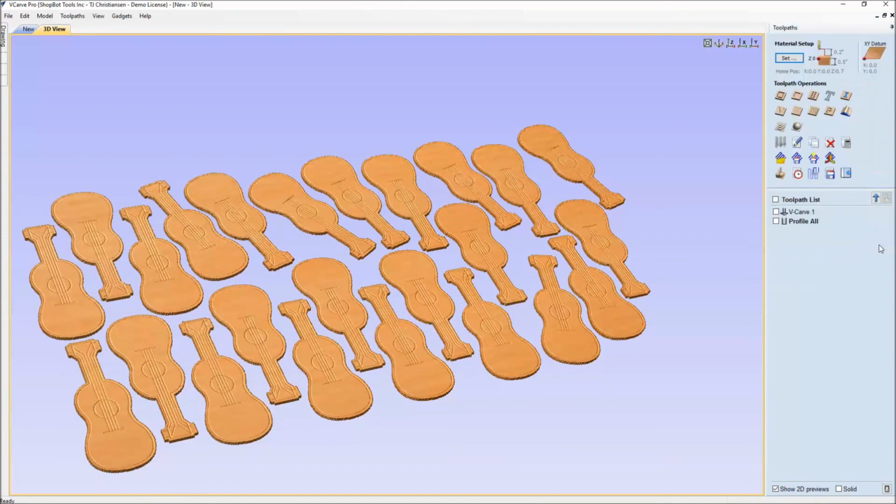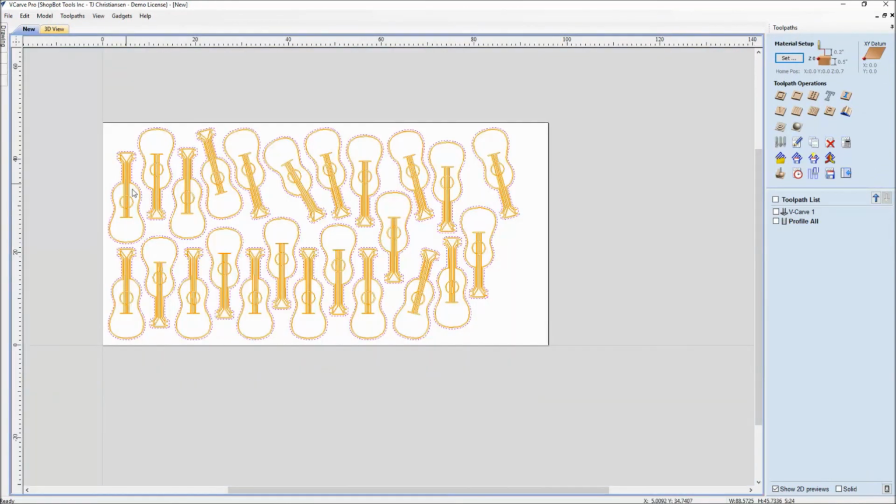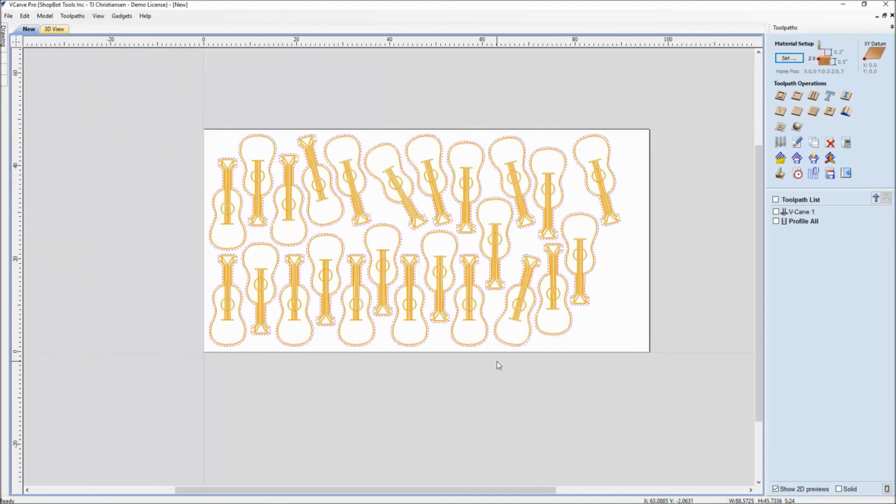What I've done very easily now is take the layers, use the layers, bring them in, and use the toolpath templates from a previous file, saved those, and was able to load this because this is a similar job doing similar projects. Instead of having to create toolpaths from scratch, I was able to do that in this type of project. Today's tutorial was to get you into the habits of using layers and toolpath templates. And again, this is for organization purposes and to help you with similar jobs to save you time.